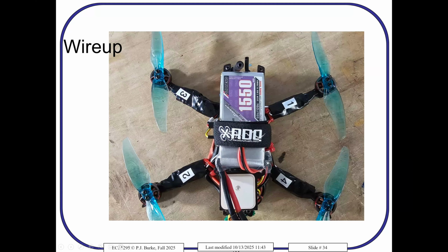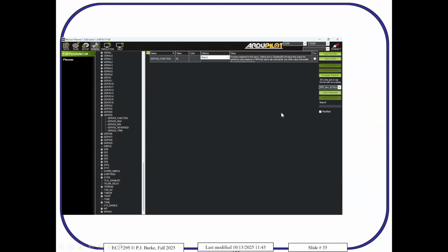This is one of the drones I built. I would advise you to label them. You're going to get so confused because you're learning a lot, you're doing a lot of building and wiring up things. And it's hard to keep it all tracked in your mind. And there's different ways of labeling things. So I would advise you strongly to label everything that you're doing, especially the numbers. So it's motor number 1, 2, 3, 4. For example, why did they do it that way? Why don't they go 1, 2, 3, 4 in a circle one way or 1, 2, 3, 4 in a circle the other way? I don't know. I just work here. So label it so you don't forget. And then 1 and 2 have to be clockwise and the other ones have to be counterclockwise.